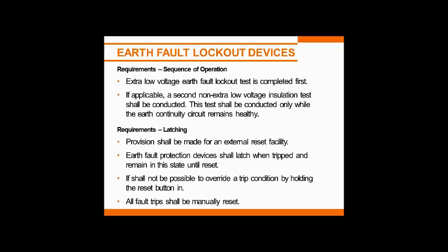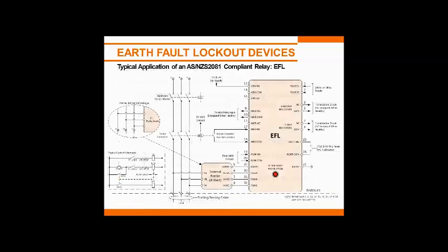Some of the requirements for latching: there's an external reset, which we do have, and they latch when they trip, and they cannot be reset until an external reset has been applied. And once again, you shouldn't be able to override the latching or the trip by holding the reset button in. And all trips have to be manually reset, no automatic resetting.